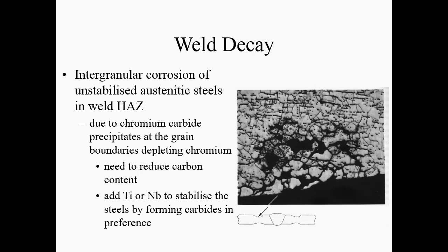These are the individual grains. You can see the grain boundaries are quite tight here, but they're really open here. What's happened is the corrosive environment has just corroded away the grain boundary material, and it falls out. And you get very big corrosion pits, very rapid corrosion.